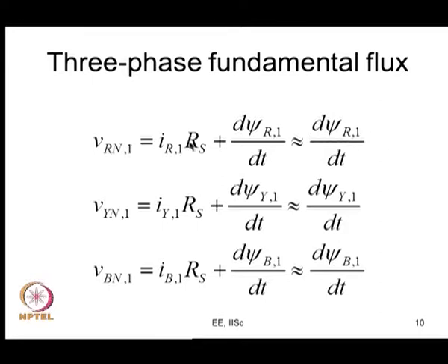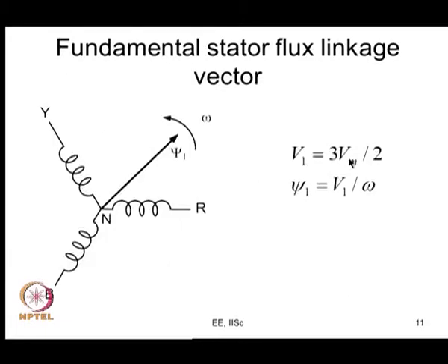So, you will have this equation, as I was mentioning the other day. This is from where you draw that V/F ratio to be constant. If the voltage to frequency ratio is held constant, then the flux amplitude would be constant. So, the fundamental one produces the fundamental flux.